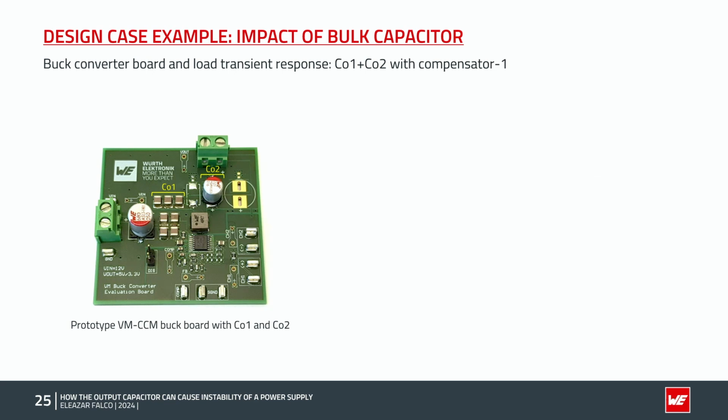And this is the buck converter prototype board, which was used for the measurements, where we can see the output capacitor CO1, the 3 MLCCs in parallel, and the bulk capacitor, the hybrid polymer CO2, highlighted here.